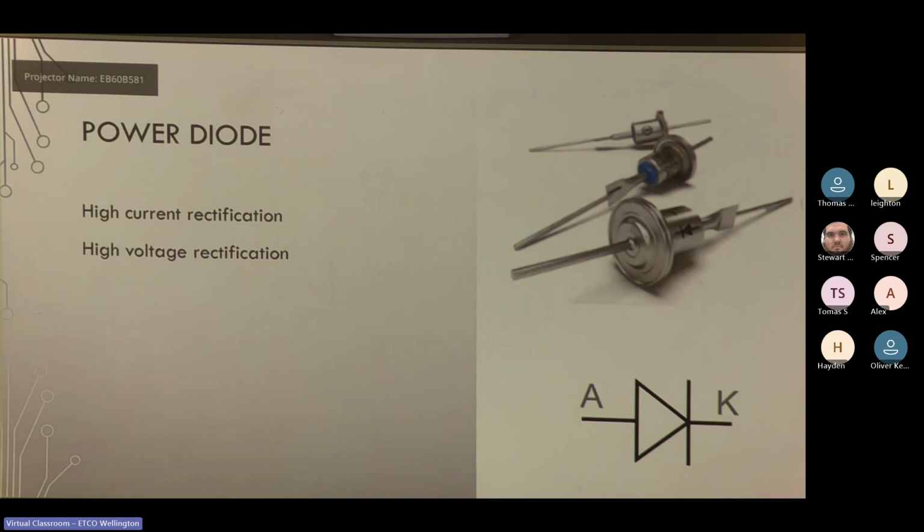There was one instance where a whole bunch of TVs got tested with 500 volts DC in an insulation resistance test, and this was too much for the power diodes in the TVs. So all the power diodes in the TVs went pop, pop, pop, and all the TVs got written off and replaced under insurance. But someone who knew a little bit about electronics opened up a TV, found the power diodes were blown, replaced them, and got about 5 or 6 new TVs out of it.